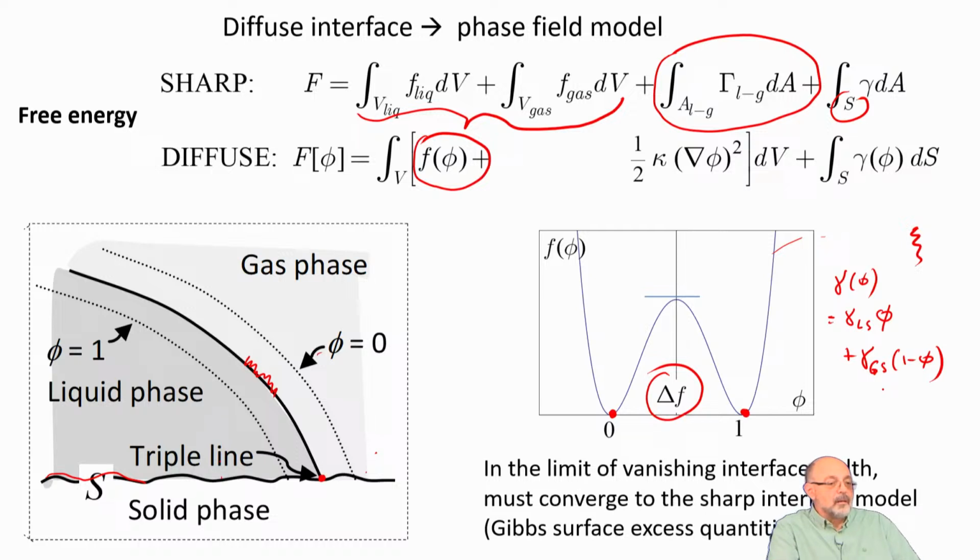Right? So why did you not take the volumetric energy of solid in this application? Because nothing happens to solid, right? Solid is just there. There's no diffusion in solid, there's no chemistry, we just have fluid flow, right? So why would I model something that doesn't change?